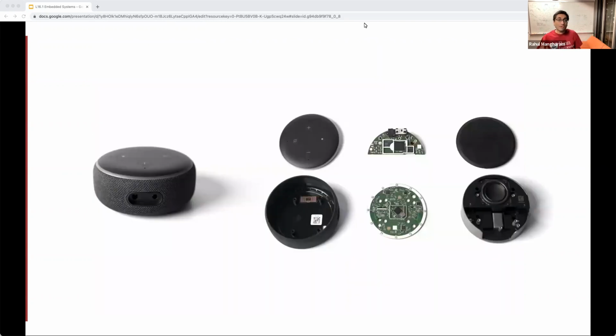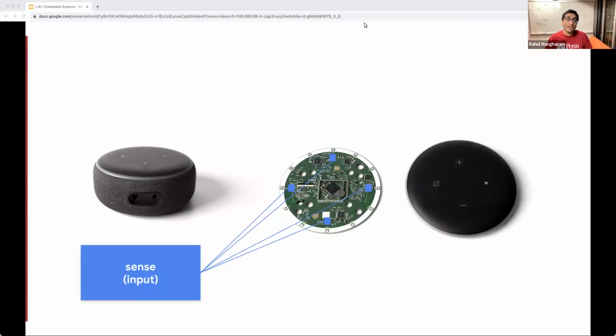So let's take the Echo Dot, since we are often talking about keyword spotting. An Amazon Echo Dot reacts to Alexa. How does that happen? If we take it apart, we see different components in there. And in this teardown, we are seeing that the microphone array is on the PCB. And there are 4 different microphones here that are the source of the input signals into the computing subsystem. These Texas Instruments microphones take the data and hand it off to the processing system.